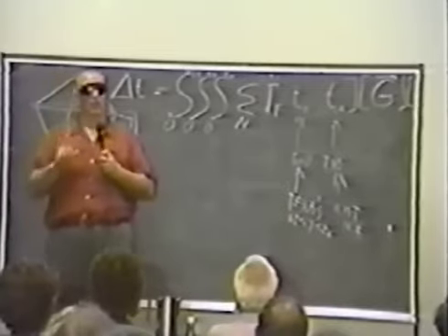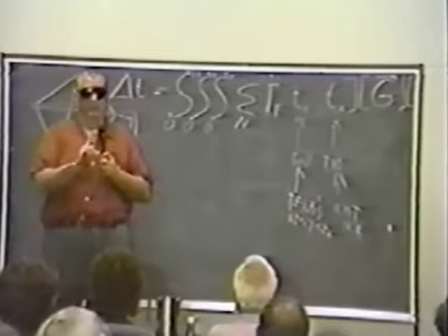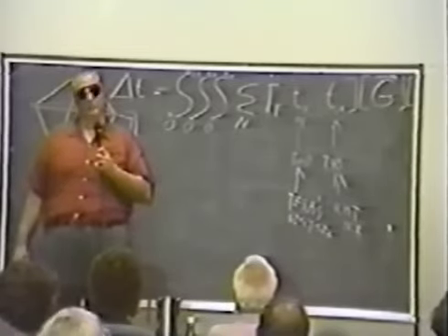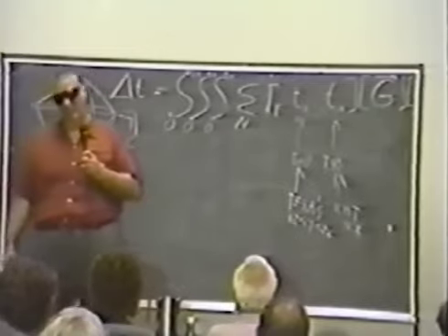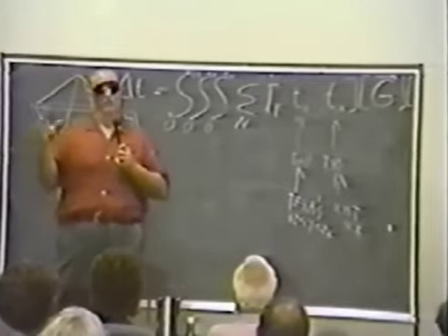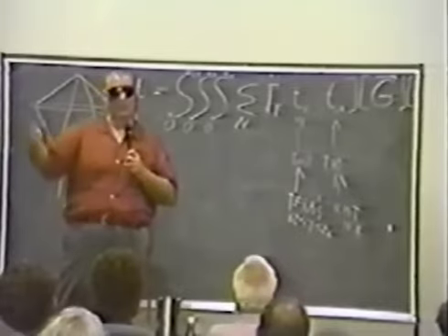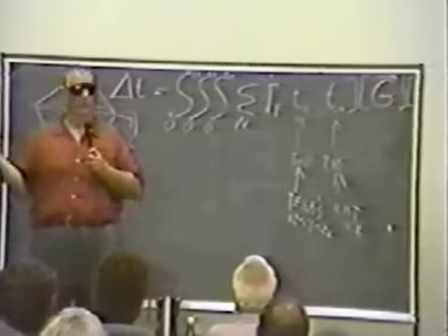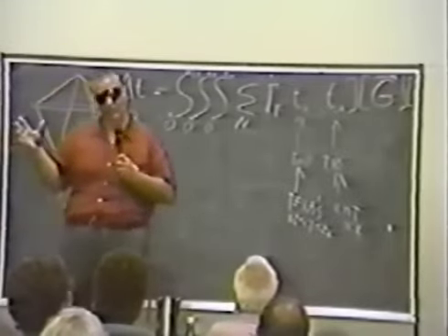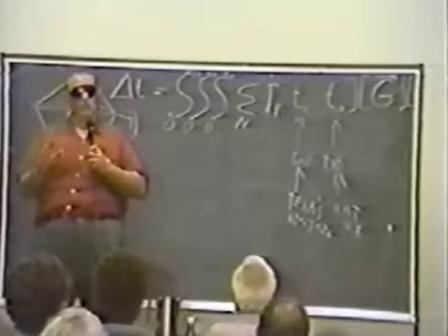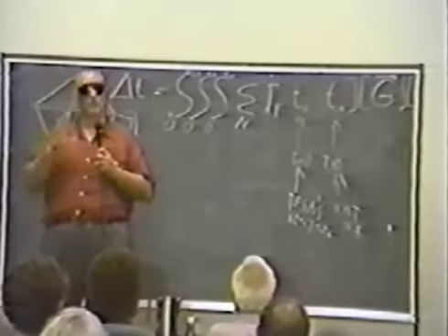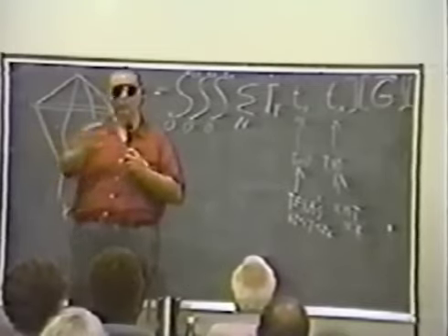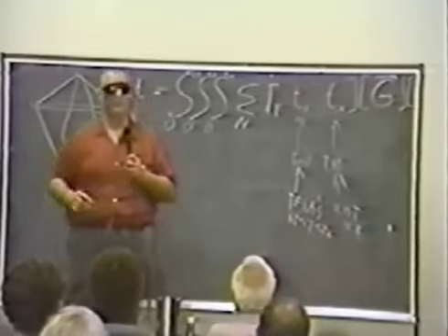Now, I've taken that reference generator and operated that thing from 58 to 62 hertz. Its output frequency did not change once it locked in. When you went below 58 hertz, 57 something, it dropped out of lock, and then the motor tracked the frequency, and when you went above 62 something to 63, same thing happened. So this generator is locking in to something besides the power line frequency, or else you wouldn't have that window where it doesn't change its output frequency.